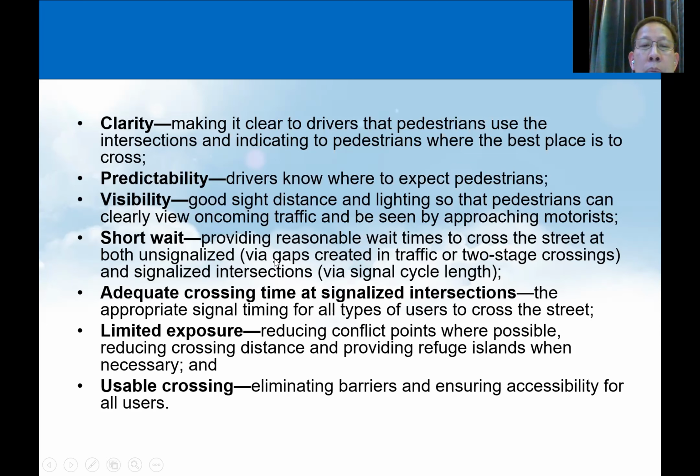Short wait: providing reasonable waiting time to cross the street, at signalized and unsignalized intersections. If many people are crossing at an unsignalized intersection, you may later on consider putting in a signal, so that this signal will keep the pedestrians safe by letting them cross the street with the red signal for the vehicles.